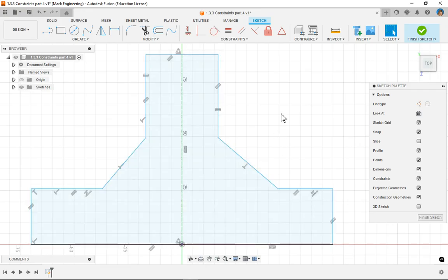We're going to add some circles into our sketch. Before I add my circle, I want to add another construction line to help me line up my circle. So I'm going to go up to my line tool again. I'm going to click line tool, my line. I'm going to go over to line type and click construction line. This time I want to go along line 2 until I find that midpoint. Again, it'll be an X and a triangle.